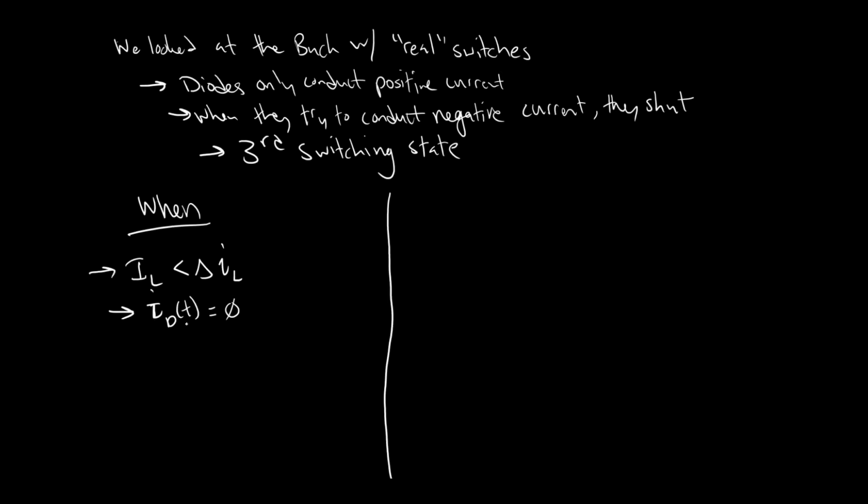We defined this new term called K, and K was 2L over RTS. Then we related this K to this other value, Kcrit, which is a function of D. Depending on if K was larger or smaller than Kcrit, we would be in DCM or CCM. And we could also think about Rcrit, so we think about R as a function of Rcrit.